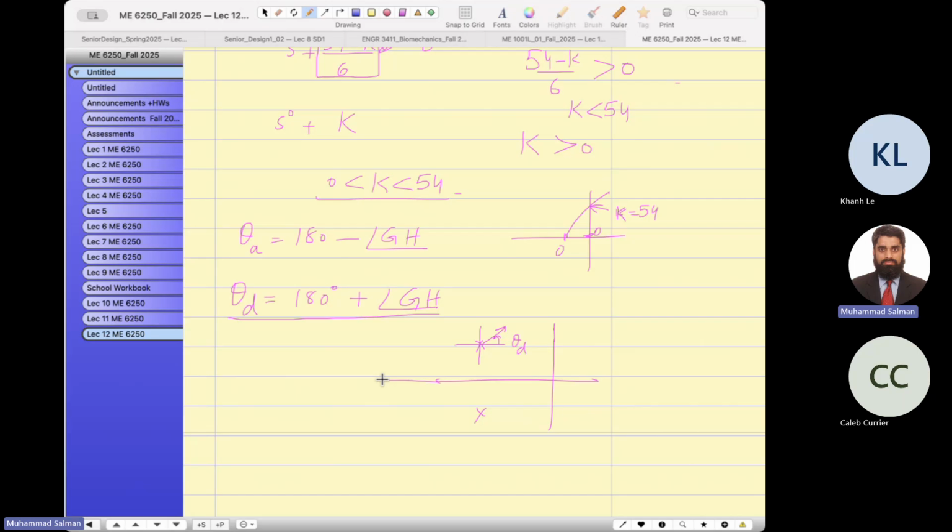And if they arrive over here, suppose these are the locations of the open loop zeros. You will draw just a reference plane here and see if the angle of arrival coming from here is, suppose, 120. So it will go like this, 120. You see my point here? It will go the same, a mirror image. You see my point, guys? So the angle of arrival is found using this formula, and the angle of departure is found using this formula.